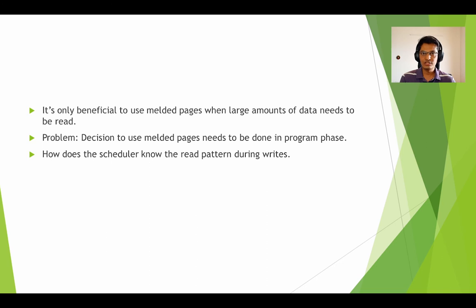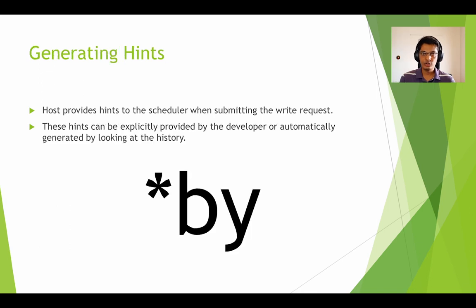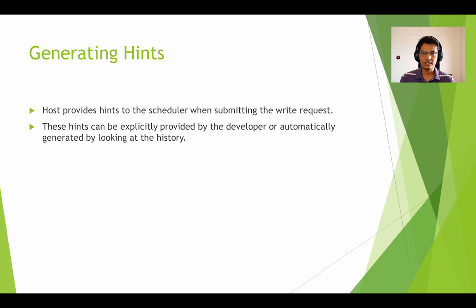Now the problem is, the decision to use melded pages needs to be made in the program phase, that is, while writing data. How does the scheduler know the read pattern during the program phase? Well, the host needs to provide hints to the scheduler when submitting the write request. This can be done using NVMe's directive support. It provides us with an ability to exchange extra metadata in the headers of ordinary NVMe commands. The proposal is to add a new directive that enables the application to declare the read patterns. These hints can be explicitly provided by the developer or automatically generated by looking at the history.